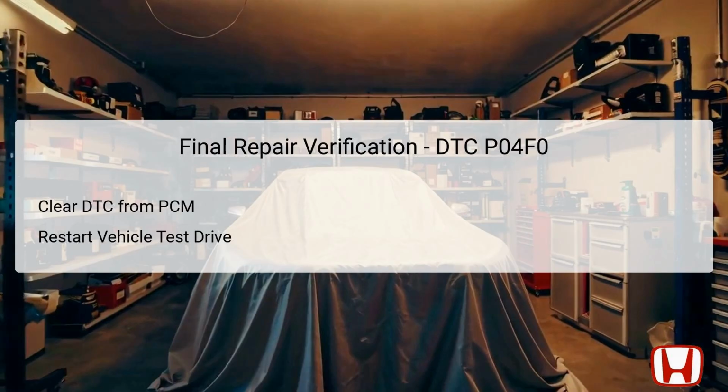Upon completing the necessary repairs or replacements related to DTC P04F0, it is essential to verify that the repairs were successful. Start by clearing the Diagnostic Trouble Code from the Powertrain Control Module (PCM) using the HDS. Following this, perform a test drive to ensure that everything is functioning smoothly, paying special attention to any signs of performance issues or emissions-related irregularities.